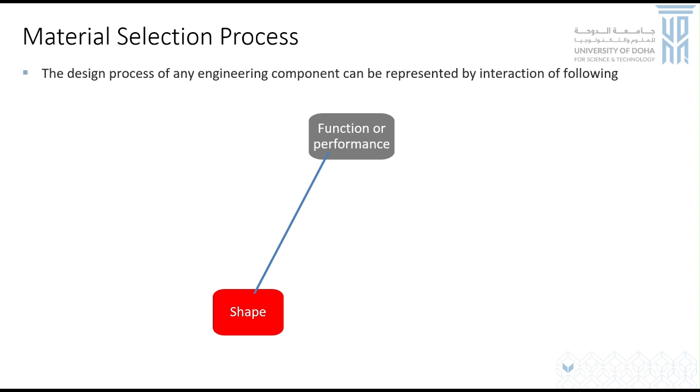Okay. So when we are now talking about that function, we can basically isolate that function in terms of basic mechanical functions if we are looking at it from a mechanical point of view, such as: is the component supporting an axial load? Is the component supporting a bending or a beam type load? Is the component under torsion? So then it's like a shaft, right? Those are the types of basic functions that we are talking about.